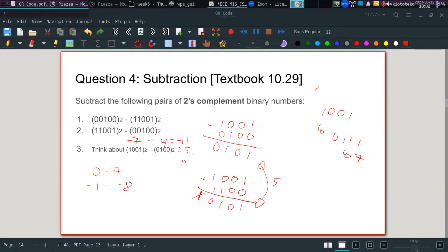But yeah, that's a problem when you define two's complement. Be aware of how many bits you are using and what the limitations are of the operations you can do, because there's a certain range of values you cannot output, no? So is there any question with this? Like this, this is -11, but it results in 5. Again, if we did this as unsigned numbers, then we wouldn't have that problem, but because we're operating as two's complement numbers, yeah. So is there any question with this?